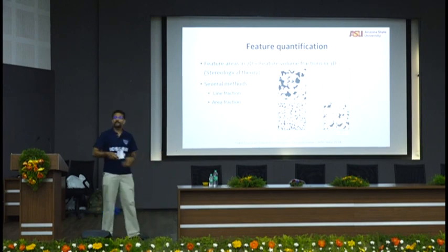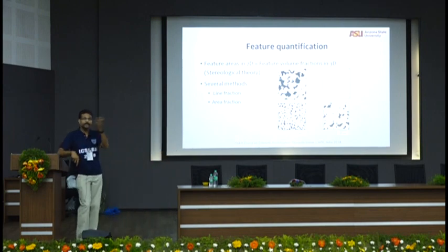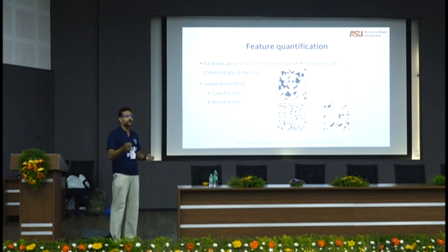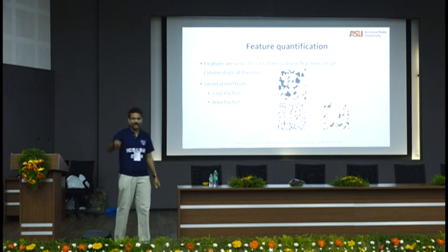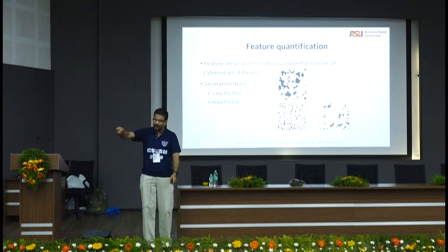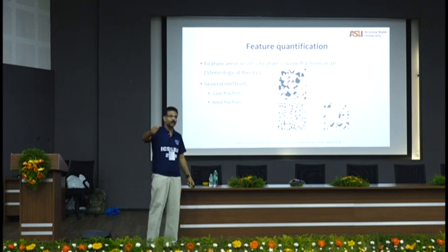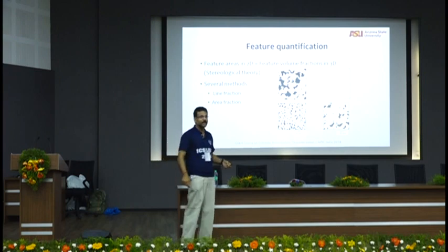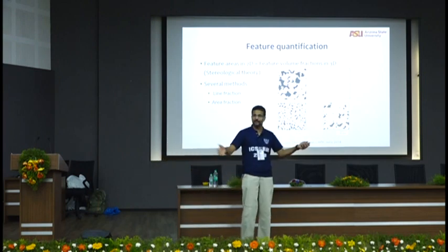So now, I saw some people doing pervious concrete stuff here. For pervious concrete, if you want to find the porosity, a lot of times how do you do it? You tape the whole thing around, or you put it inside an envelope, you seal the sides, you add water, and find out exactly how much water you have added. By the time you're adding water through the top, some of it is spilling through the sides. You don't know how much you're adding because your sleeve is not tight and something is leaking through. And you do 5 samples, and it's giving you 5 different values with a standard deviation of 100%.